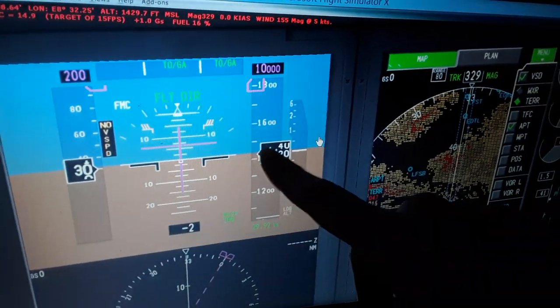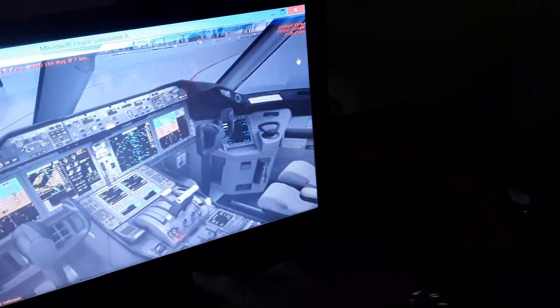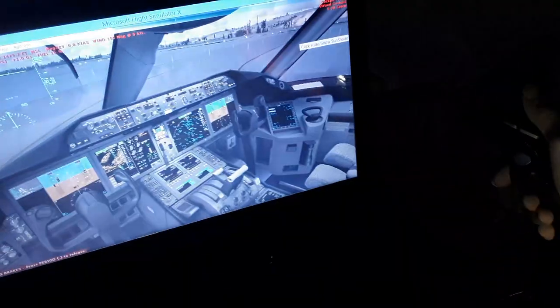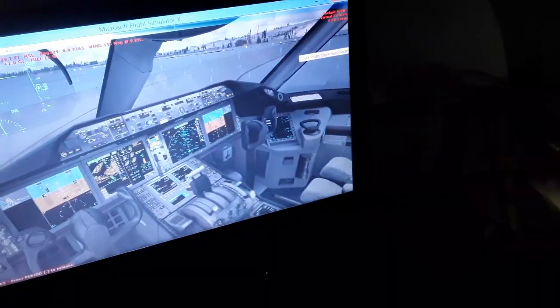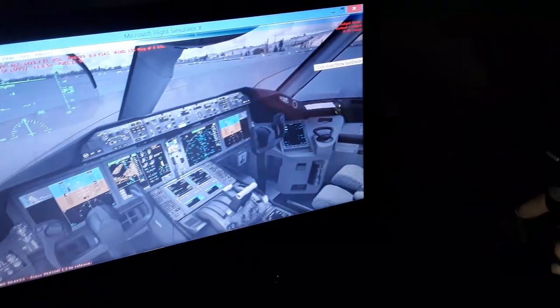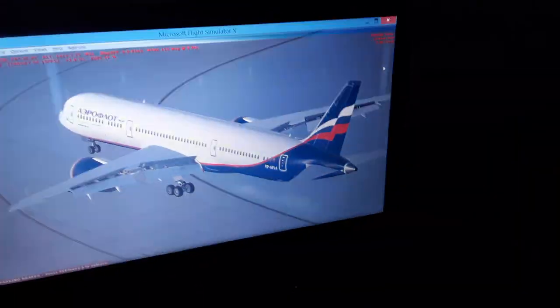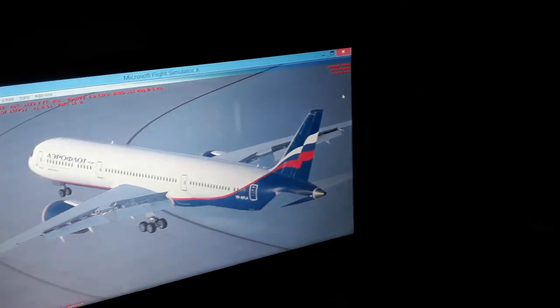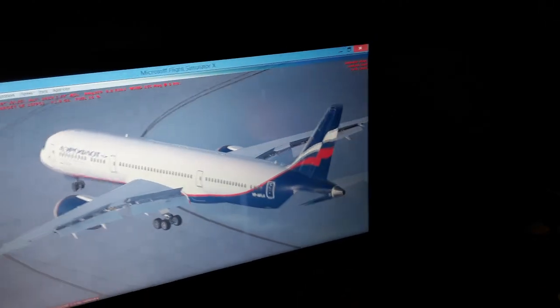Also, you need to pay attention to the angle of stall. So if you stall the aircraft, you apply the side stick down in the Airbus, or the yoke down, to decrease the angle of attack, and then you advance the thrust levers forward to increase the airspeed. Also, in the Airbus you may have the alpha protection system, which is going to lock the takeoff ground automatically. So over here you can see the aerodynamic chord.